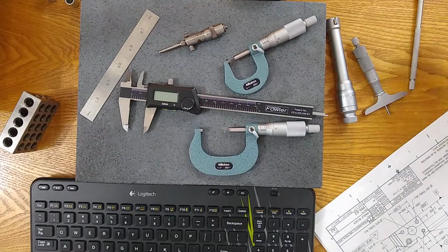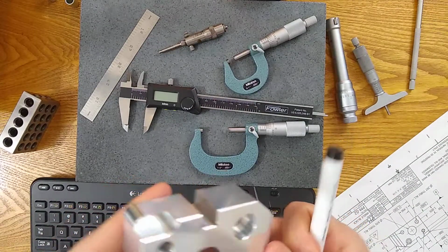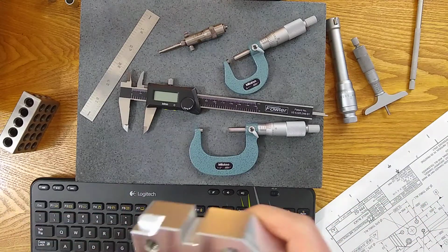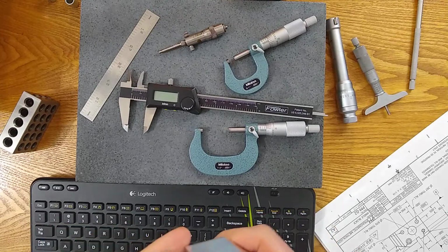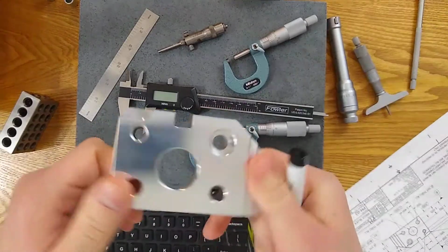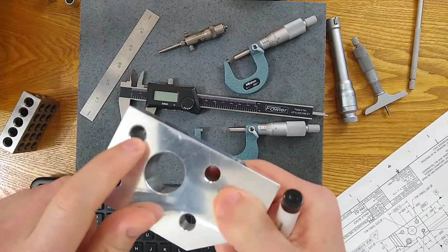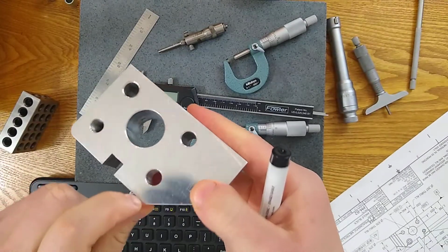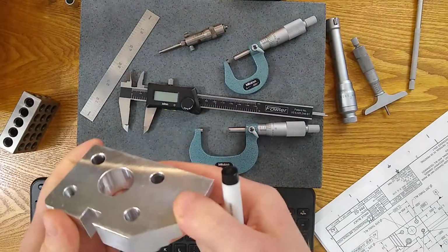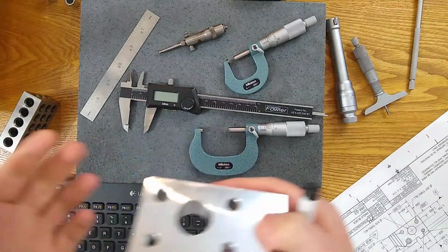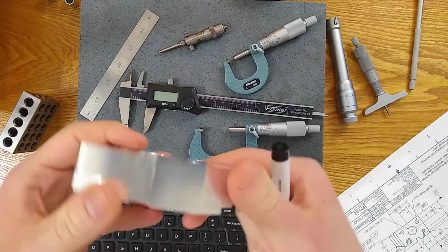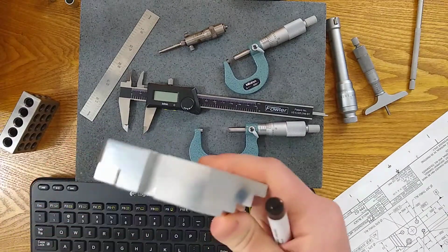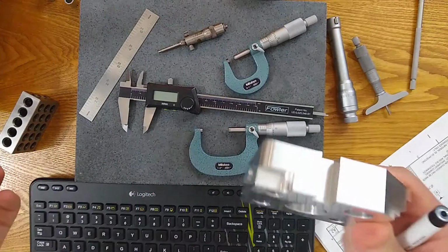Other things like burrs, sometimes there'll be sharp edges left over and your gauges will grab onto those that are protruding and messing up your measurement, and they should be removed. Once they're removed, everything's okay sometimes. If you watch the hole inspection video, I even found a burr inside. Can't remember which hole it was now. I think it might have been this hole, a burr that stopped the pin gauge from going through. But otherwise, once that burr is removed, I've got tons of clearance, but the go side wouldn't go. It was just right on the edge of this tolerance zone because of the burr. When the burr is removed, I'm going to be back in the middle of tolerance, and everything will be great.